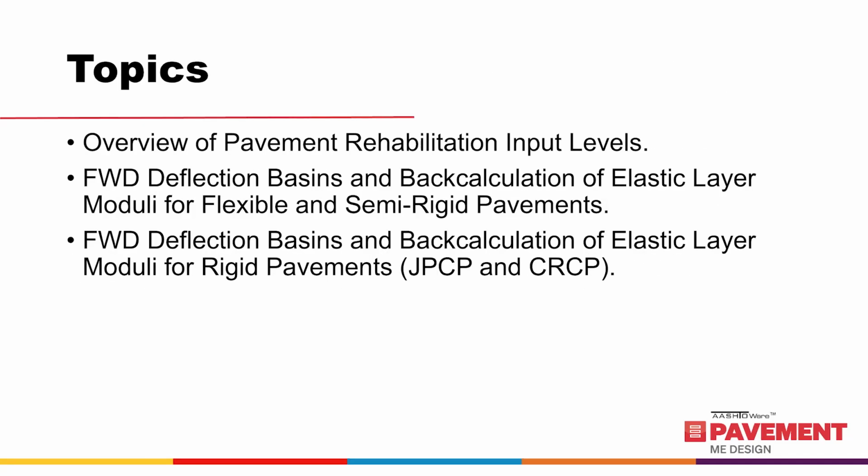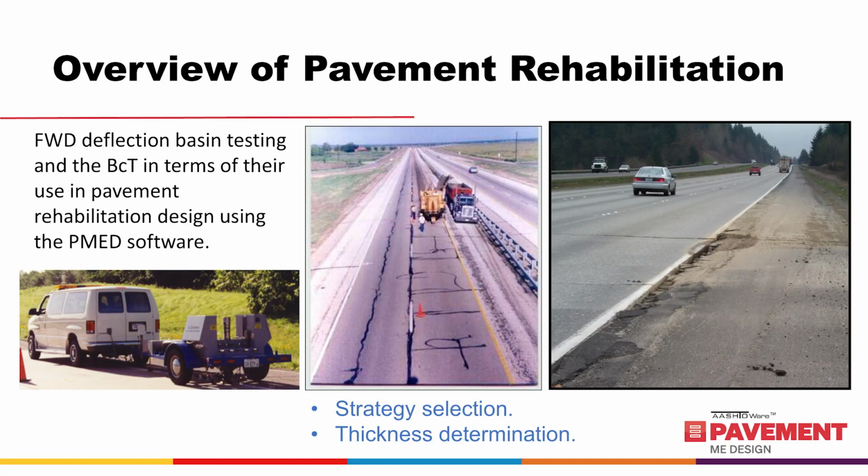The topics that will be covered in this session are overview of different rehabilitation design input levels used in the PMED and identify the differences between the rehabilitation input levels 1, 2, and 3. Discuss the FWD testing and back calculation of elastic layer moduli for flexible and semi-rigid pavements. Also discuss how FWD testing and back calculation of elastic layer moduli is performed for rigid pavements, JPCP and CRCP.